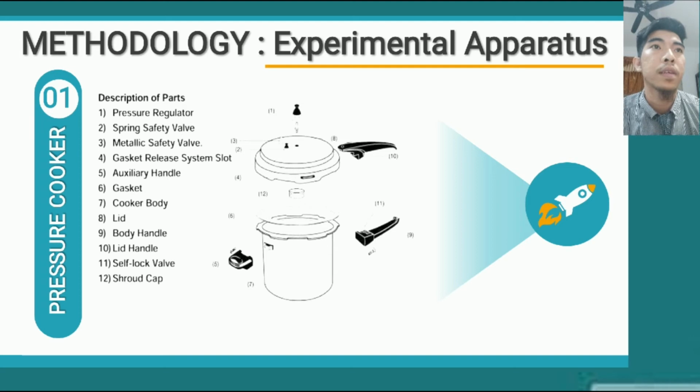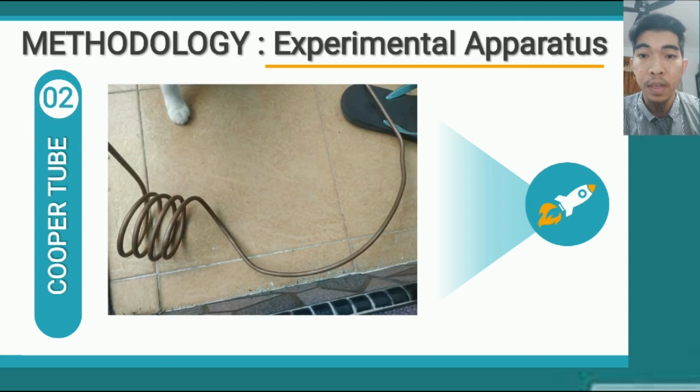Okay, and then the second necessary material is copper tube. Copper tube is the most common material used in heating systems and as a refrigerant line in heating, ventilation, and air conditioning systems, or HVAC systems. As time goes by, copper tubing is slowly being replaced by cross-linked polyethylene or PEX tubing in hot and cool appliances.